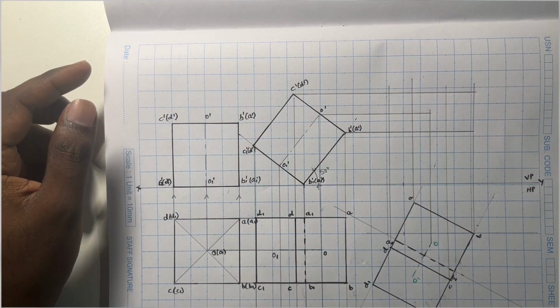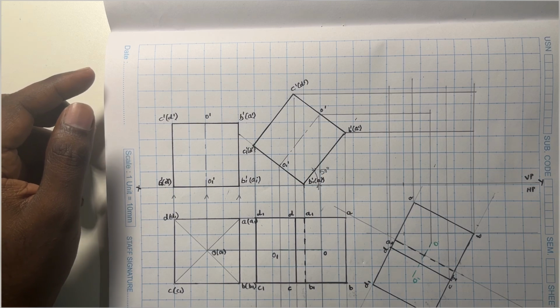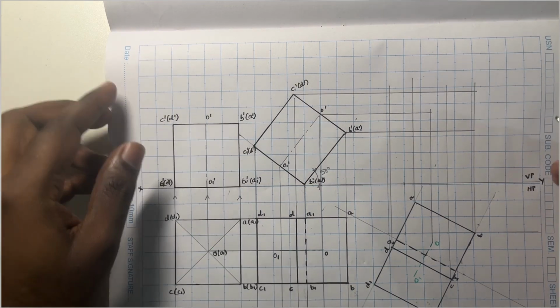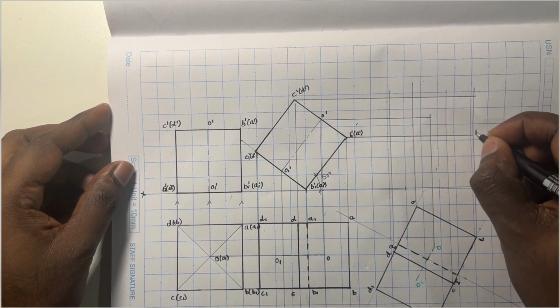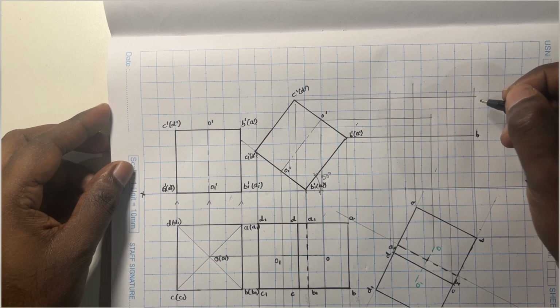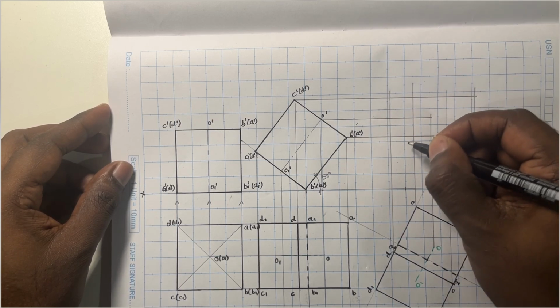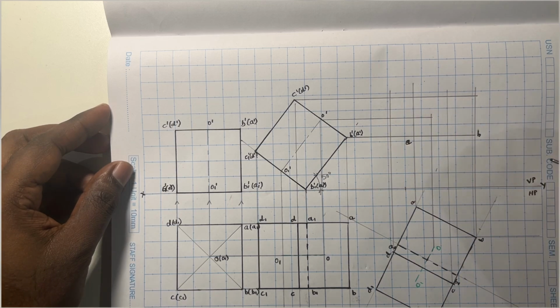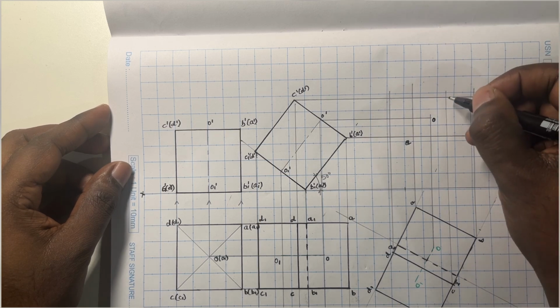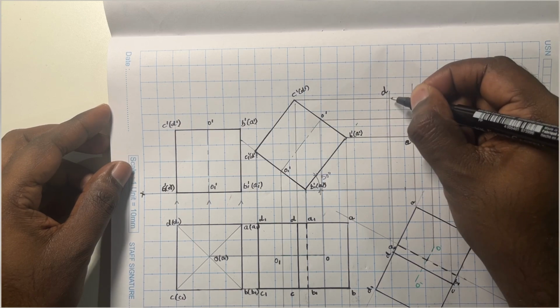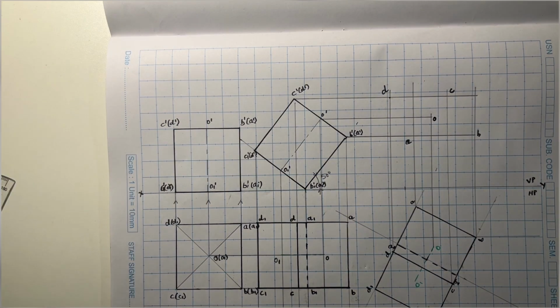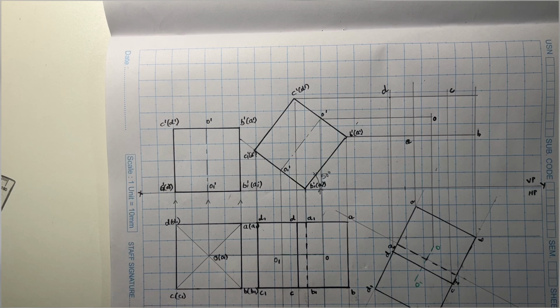So the points of intersection to complete the cube in the front view. This point is from B and this is from B, so this is the corner B of the top face. Next is this corner A, and this is the corner A here, the point of intersection. Well, this is the axis O, and next I've got the corners C. So this is the corner C and this is the corner D. I'll just complete the other positions later, by joining the edges.